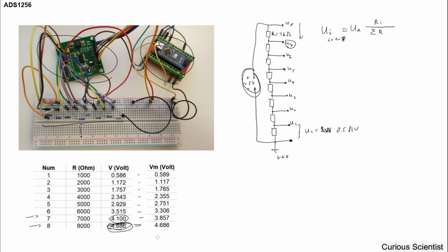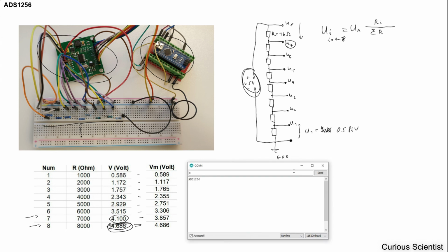Of course it will not be the same, because the voltage can change a little bit, and then also the resistors are not exactly 1 kilo ohm values, which is of course can be expected. But what we can do now is we open the terminal and then do a measurement or two to see what is the value. So we have the terminal here, and I just want to measure the 8 channels.